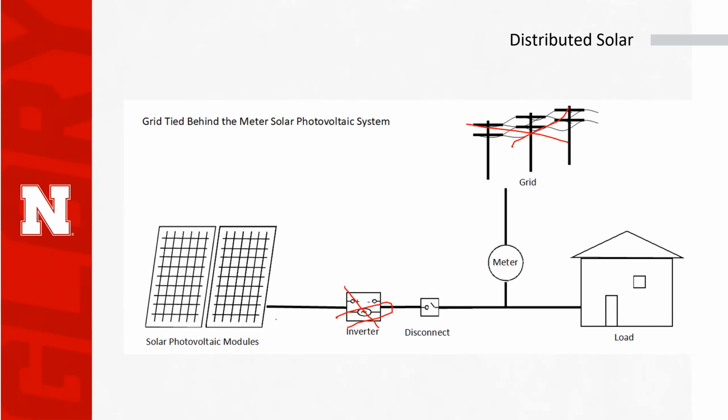You have a big solar array that is trying to generate if it's sunny out, but the inverter is saying, I don't see the grid, and when it doesn't see the grid, nothing is going to happen. So you do not have backup power if you do not have batteries. I tend to not like batteries, mainly because they are very high cost. And what are they providing me? They tend to provide me with backup, really backup to a very robust grid.